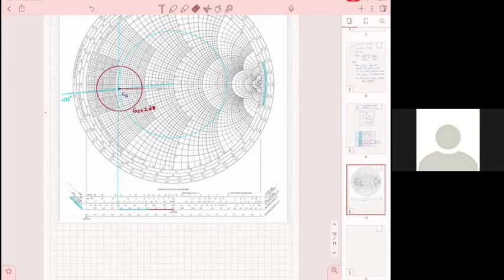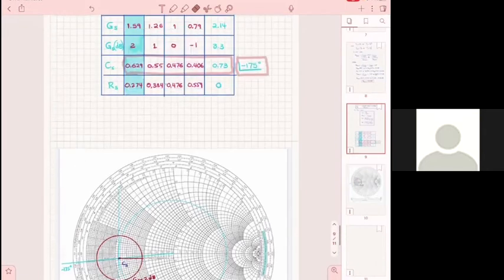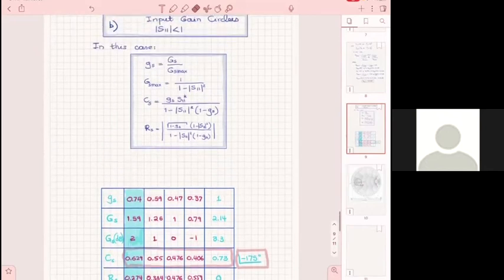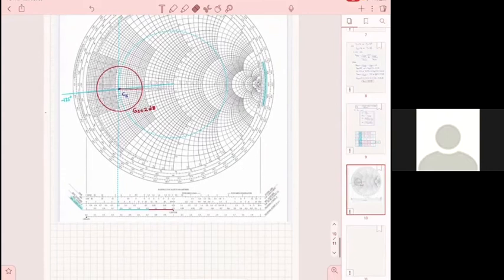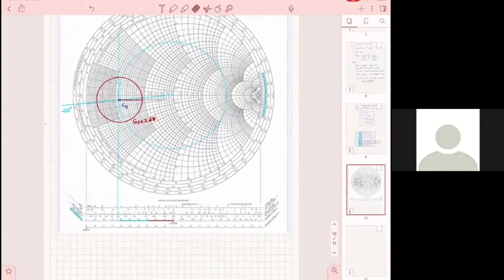It is clear, but I have a question. For the output matching network gain, we also do the same procedure, right? Yes, exactly, but the equations are different. And then we find the mutual area between the gamma S and gamma L circles with the noise.